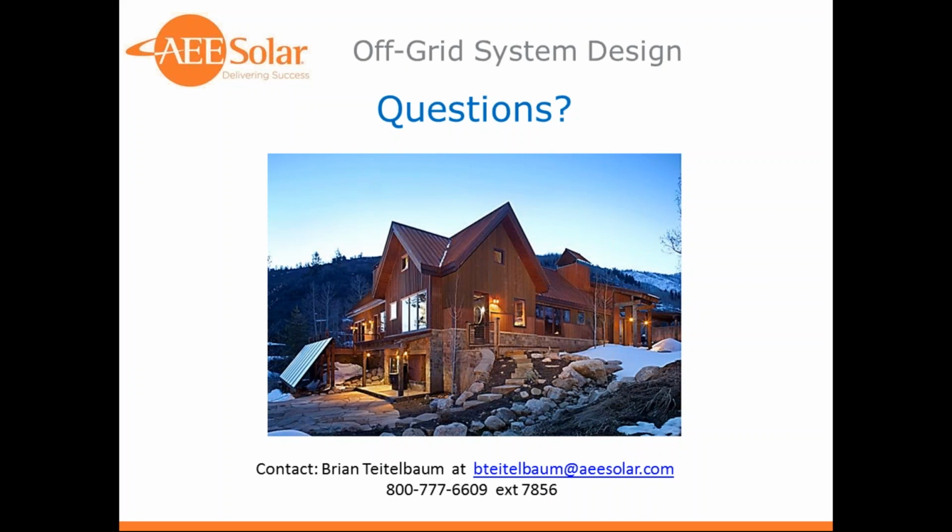Well, that's interesting. Another type of off-grid system that I didn't really talk about in this presentation is essentially an AC coupled system for off-grid, where you have PV modules with a grid tie inverter, and it could be microinverters, it could be full-size string inverters, and they connect to a battery inverter. You essentially have 2 inverters in this system on the AC side rather than DC coupled at the battery through charge controllers. That'll be the subject of another webinar.